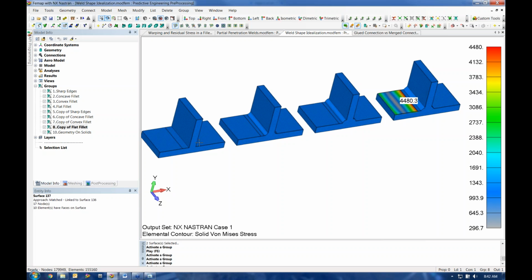Before we get into the actual stresses, we want to make sure that we have the right stiffness and the right load transfer. But beyond that, once we get into investigating stresses, a lot of the post-processing methods aren't going to have you pulling right at the weld. So it's not quite so critical. And as we'll see in a little bit, the stresses right at those notches is not something you want to chase. You can spend endless amounts of time trying to get convergence there, and it's just not going to happen for you.